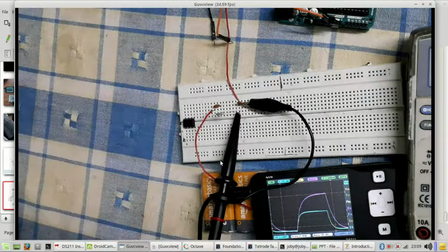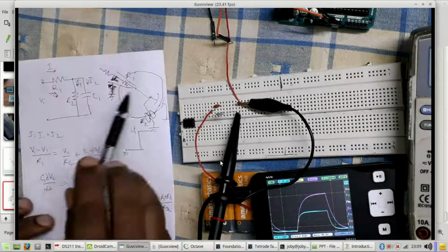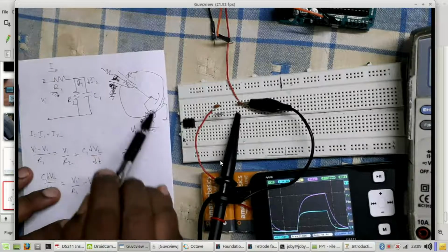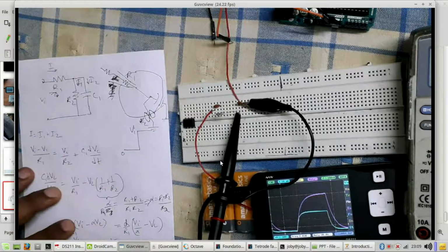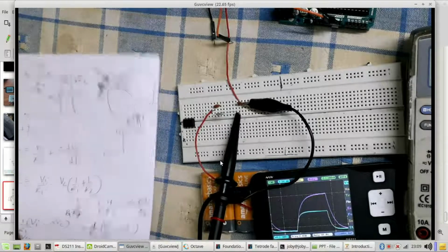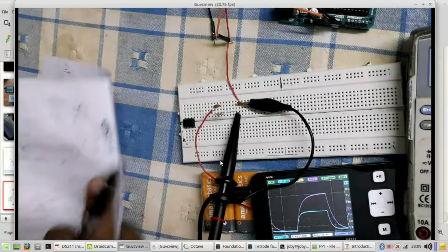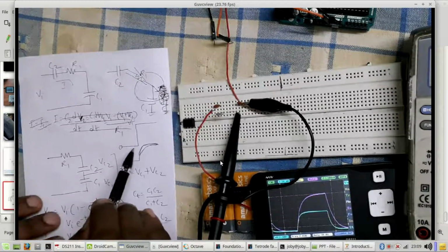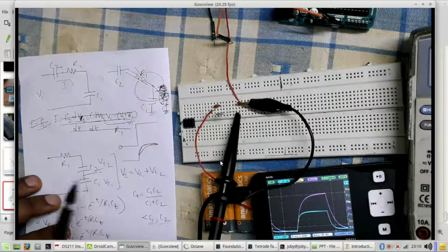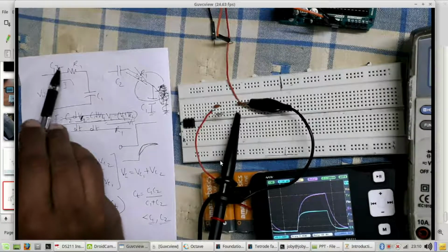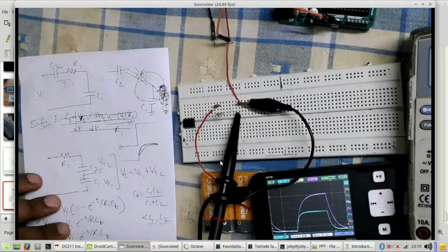We have looked at how the time constant will change when you have some conductances in parallel with this capacitance, and that is done by analyzing the circuit. We saw that the time constant decreases, and when you have to compensate for the capacitance to make a more rectangular waveform appear across the cell membrane, you need to do compensation. This is a simple example of doing capacitance compensation, and we saw the effect of that compensation in this experiment.